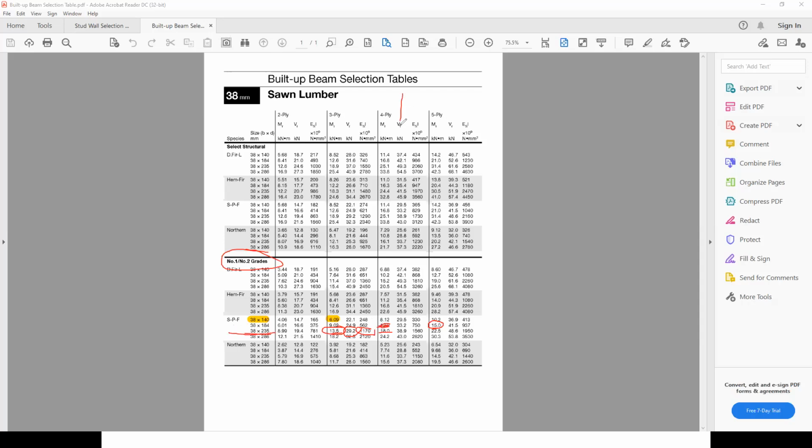And what's nice about choosing a 3-ply is that if you look at 1-ply, 2-ply, 3-ply, okay, this here is 38 times 3, and that gives you what? I think it's 114, okay, and therefore, and your 2x6 wall is 140, so it's going to fit nicely inside the wall without bulging out. So it will fit very nicely inside the wall. You understand? So that's what's nice about a 3-ply. If you go to 4-ply, well, you know, it's going to be a little bit of, okay. So that's a good choice here.